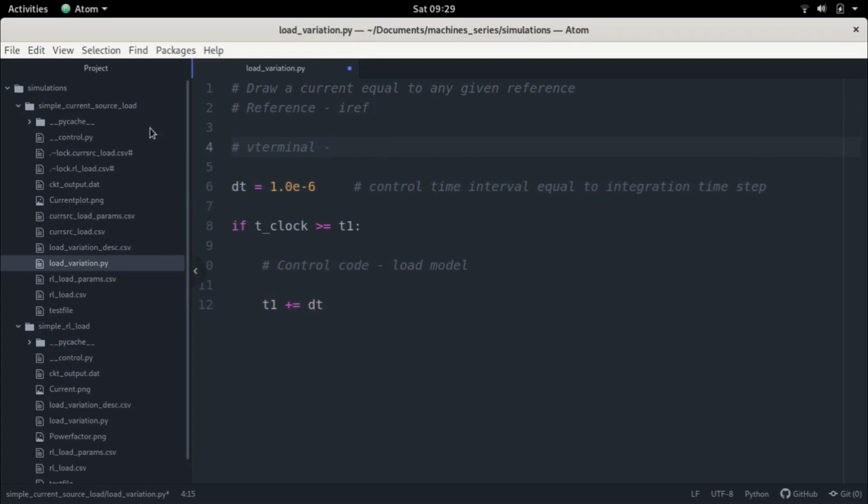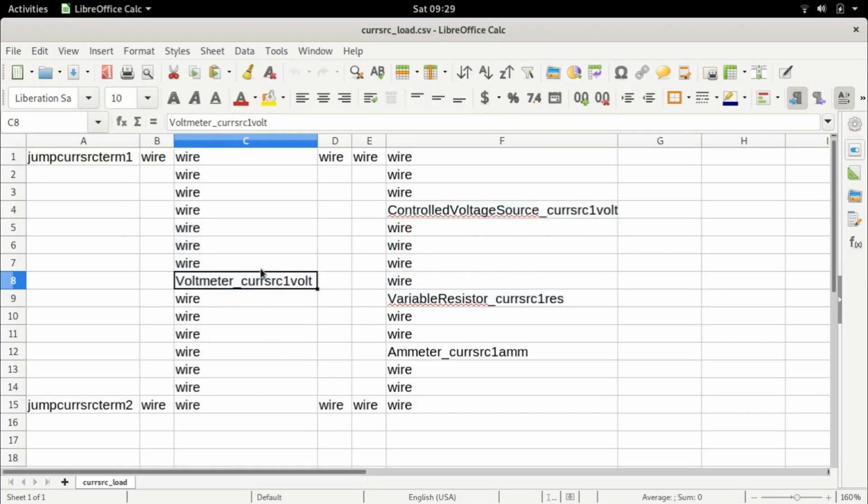So if I were to write this Kirchhoff's voltage law, and of course, as I already said, the positive terminal of this voltmeter is upwards, right? So that means if I apply Kirchhoff's voltage law in the clockwise direction, this will be taken as positive. And if we take this control voltage source with a positive polarity upwards, it becomes negative. And of course, if the current we are taking as the downward direction, then this current multiplied by the resistor is also negative, because we are in the direction of the current, right?